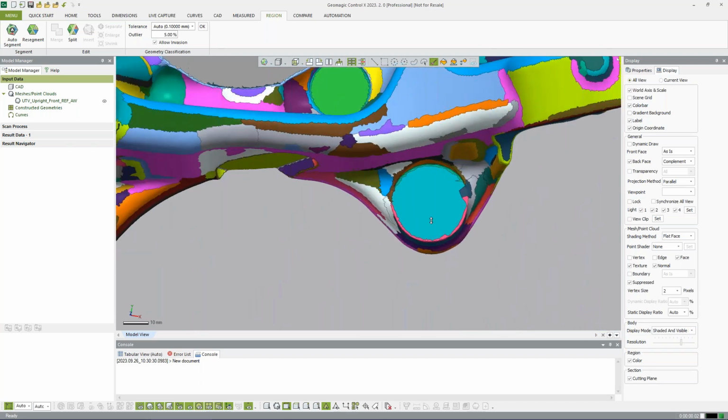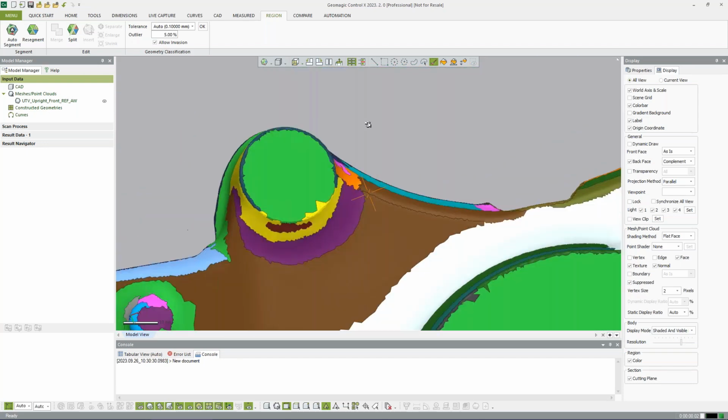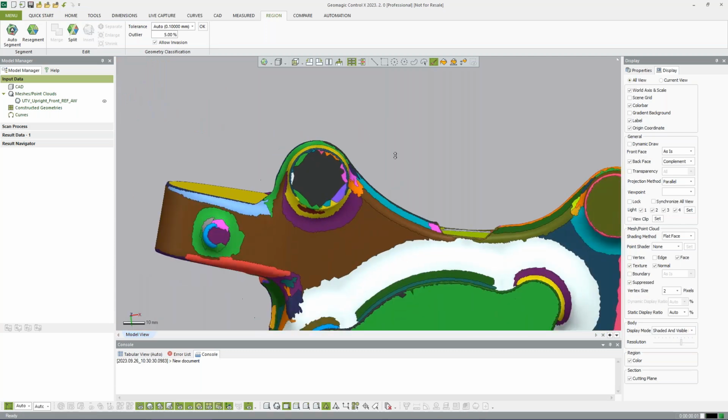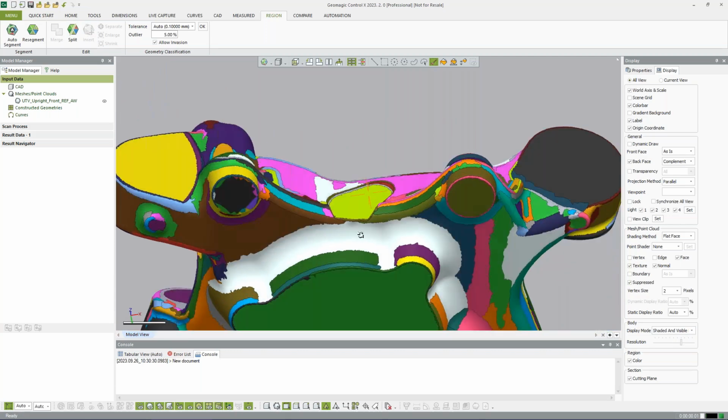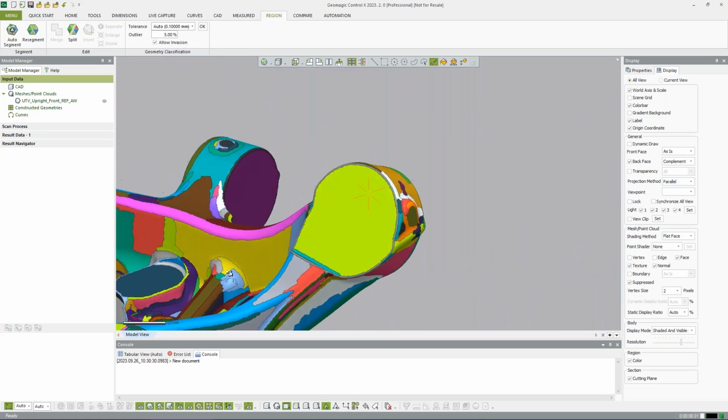And if I'm worried about any data encroachment on some of these other things, I don't remember where I saw that, like on the bottom here, again, maybe we won't use the whole face. We'll just do something like this. And you can see the triangle tessellation on some of these flat planes is a little coarse, but we're going to do something like that, just get away from edges. That was already pulled back pretty well.